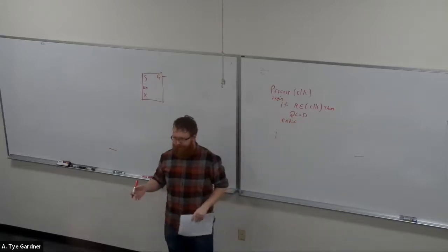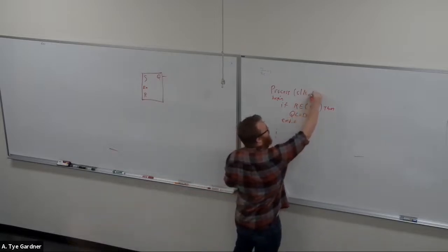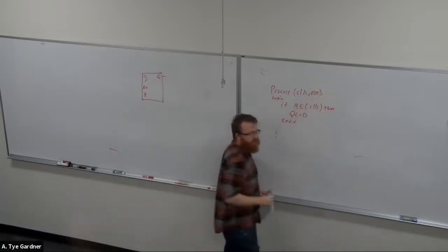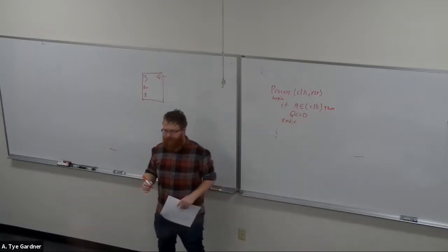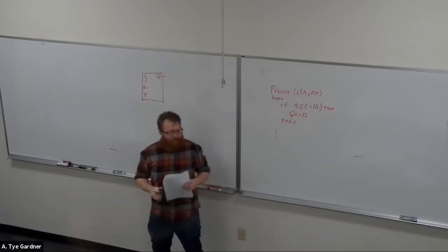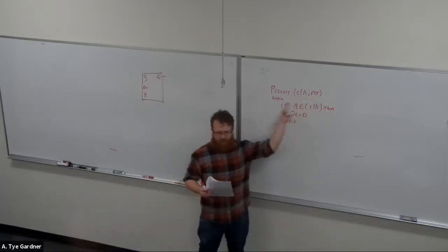You should be able to do something like, remember that if I add a sensitivity list on the reset, have I talked about resets much? I don't actually remember. It's okay. Anything else I add on reset is going to trigger this process. But if the reset changes, this won't change.